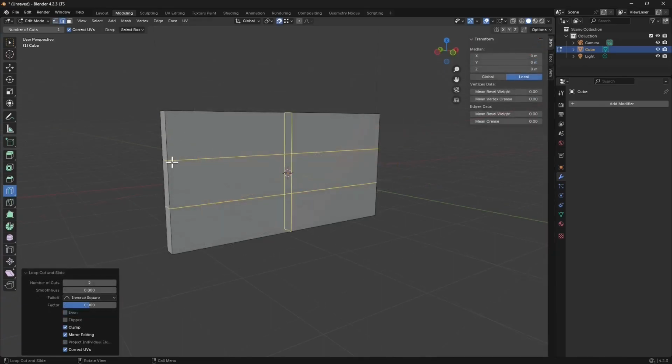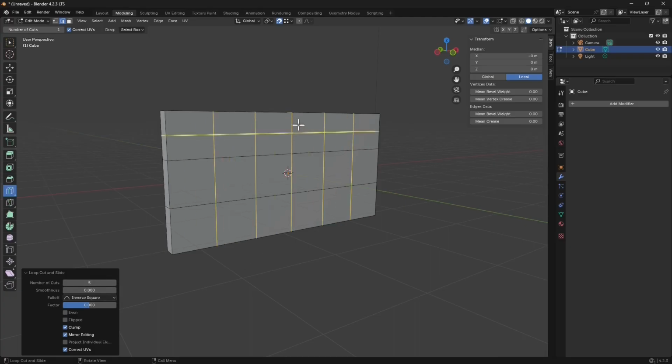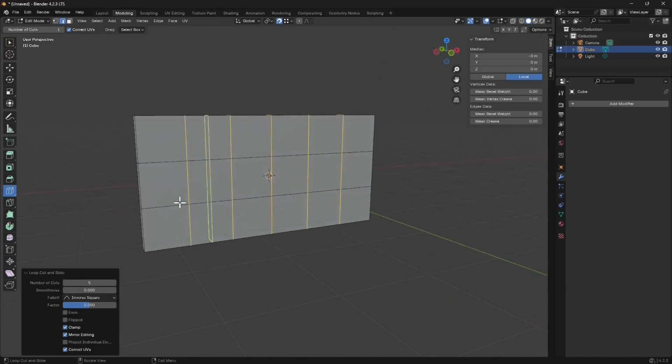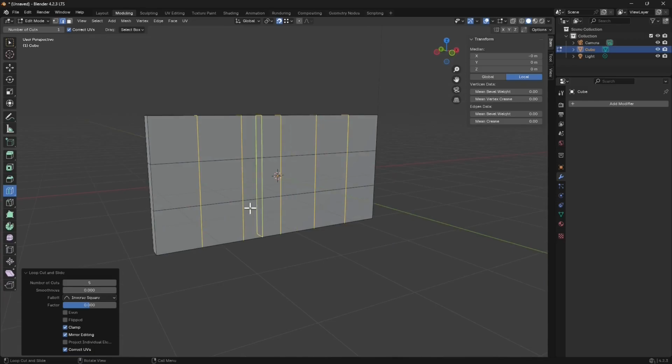And then I'm going to do this vertically too. So I'm going to select, and now I have three stripes of 1 meter. If I cut right there and divide into 5 cuts, I will have exactly 1 meter faces from every side. So I'm going to increase this to 5, and you can see now I have all squares, and this will help me a lot to do something modular using 1 meter as the unit, as the module.